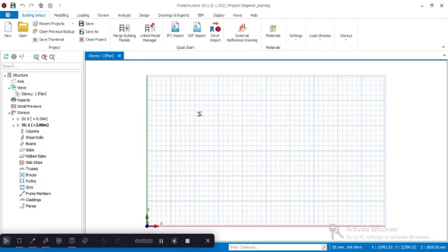Example, properties, delete, etc. Then pressing escape will deselect all entities. So now zoom and pan. All the instructions are there. To zoom the zoom window, Control plus W to zoom into the area defined by dragging a rectangle. Previous window, Control plus O, that's to zoom to the previous view.